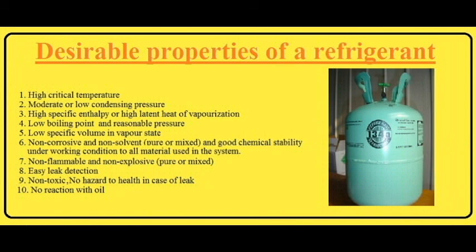Low specific volume in vapor state, to reduce size and increase efficiency. Non-corrosive and non-solvent, and good chemical stability under working conditions to all materials used in the system. Non-flammable and non-explosive, to avoid fire or explosion if there is a leak. Easy leak detection, non-toxic, no hazard to health in case of leak, and no reaction with oil.